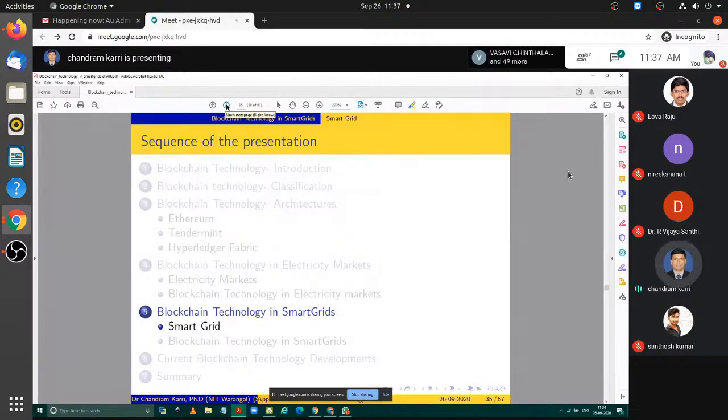Broadly speaking, in the electricity market, like in deregulated power markets, there will be a change from vertically integrated utilities to deregulation. First, look at the traditional operation: load should be predicted, then you have to look into how many generators are required to meet the power demand, and that amount of power will be generated by the selected generators. That is the tradition. In deregulated power markets and current electricity markets, what is the issue? Load is not the matter. Here the issue is how important the price is.